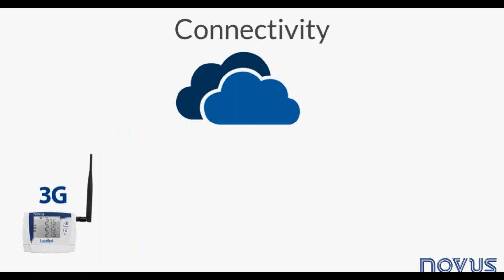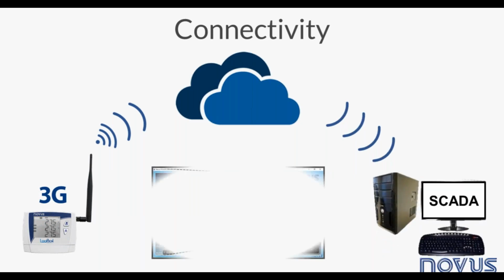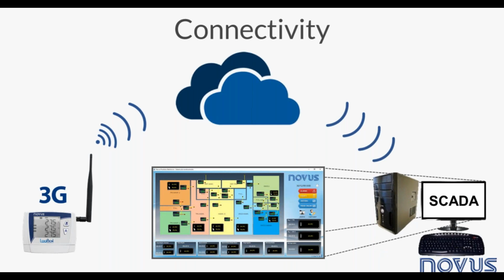A second solution is using SCADA software for accessing data. Currently, we have available a LogBox 3G communication driver for the Elipse SCADA system. This implementation can be done under request for any SCADA or proprietary system from the customer. We have a DLL that bundles the entire task of communicating with the LogBox 3G through the internet. This DLL can be used to pack drivers for any other SCADA or used by customers who want to integrate with their proprietary software.